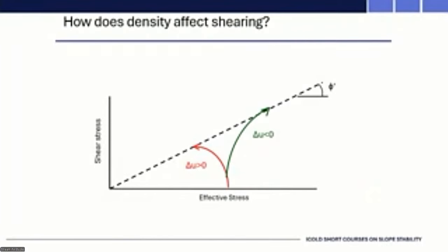So the line on the right, it's dilating. We're generating negative excess pore pressures, so it's veering away to the right, and we get to that limiting stress condition, which in this case is the critical state condition, the MTC or phi-dashed, at a higher shear stress value than if you did a drained test. You tested the sample slow enough that you generated no excess pore pressures. You would hit that dashed line when the 1 in 3 slope intersects that line, which would be somewhere between those other two lines shown there.